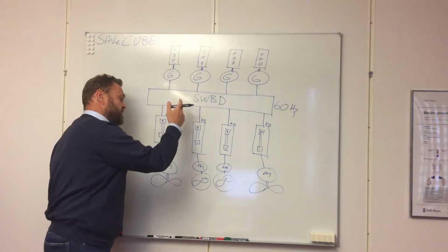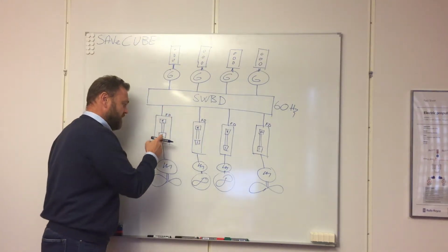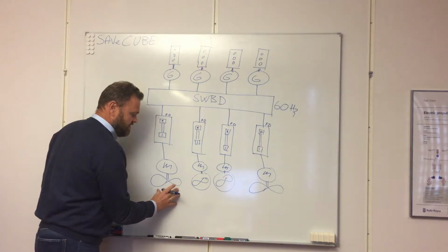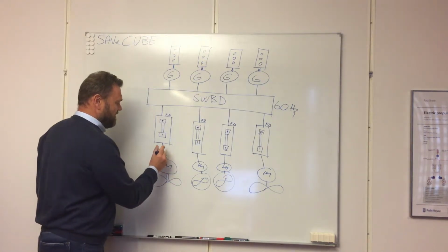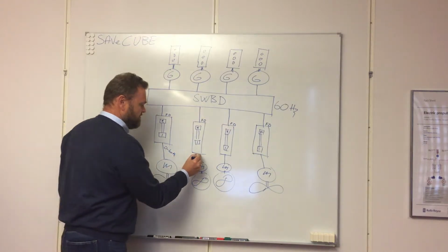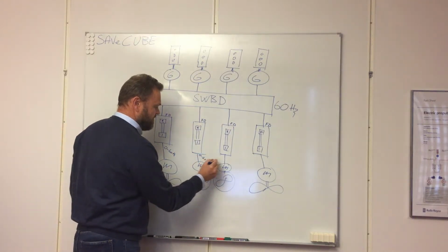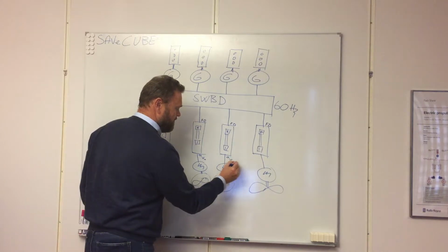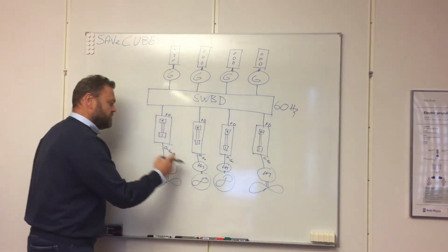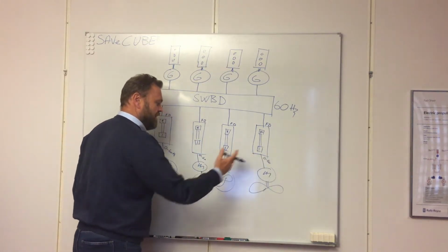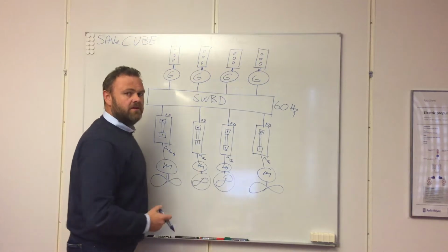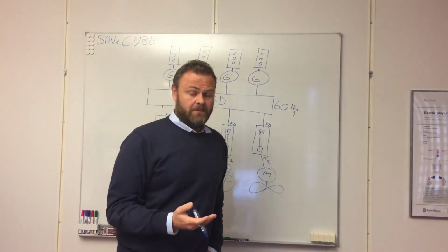And that is the reason why we need a frequency drive, because we want to regulate the speed on the propeller. So we need 0 to 60 Hertz on each of them. All these frequency drives will be able to regulate the RPM on each propeller.